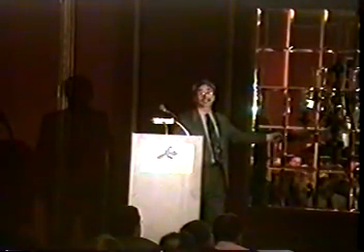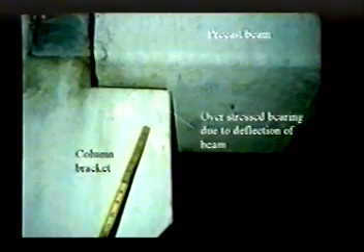Well, this is a long precast girder. If you look at the deflection of the girder, you have rotation at the very edge. On the rotation, we got high bearing stresses right here, right at the edge. And that high bearing stress caused this crack. Okay? Same structure, similar cracks, different problem. The repair of this one versus the repair of the previous one, they may be different. I don't want to get into what the actual repair is, but you've got to go to the source.